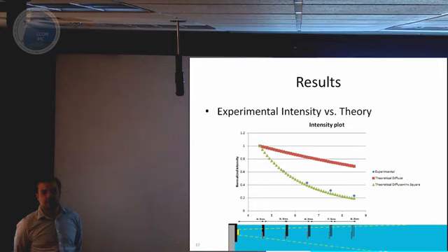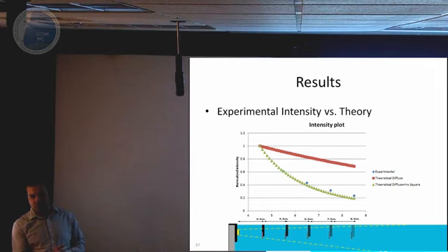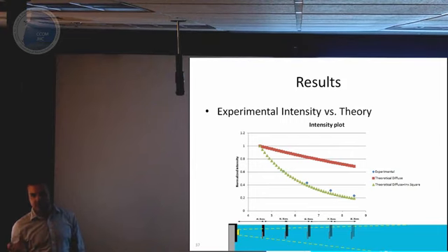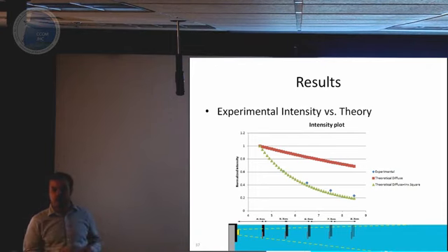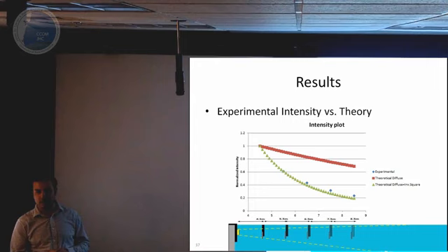The sensing part basically consists of the follower ROV. It's going to have a light detector module on its front, like you said, and it's going to detect the incoming light field from the leader, which has the light source at the bottom of its crest. Based on the intensity changes received by the photodetector elements, it's going to determine if there is motion or not. If it sees the light field getting over to the edge of the array, it's going to move to keep it in the center. Exactly.